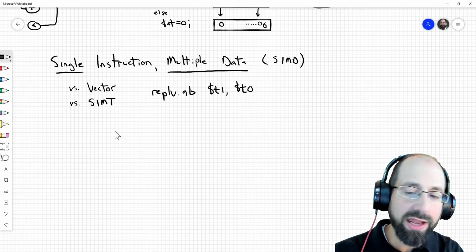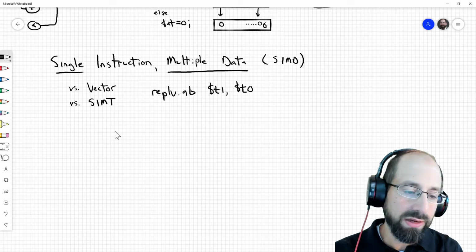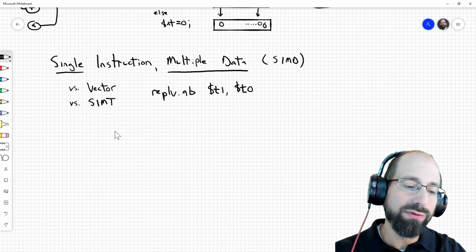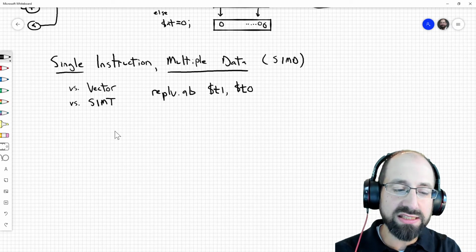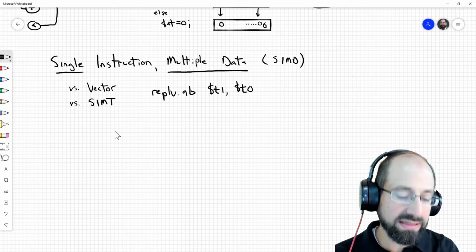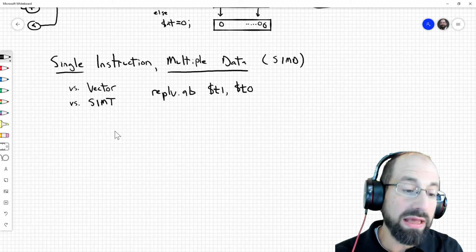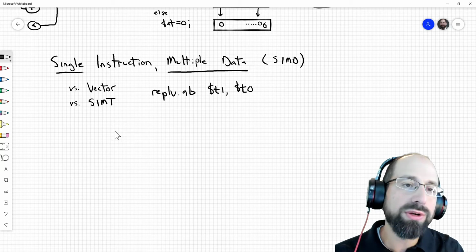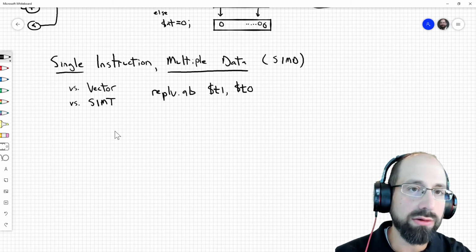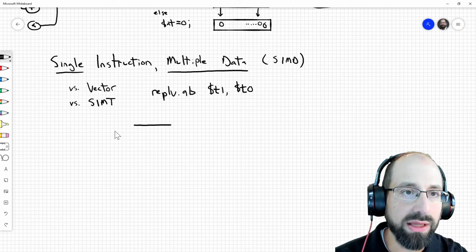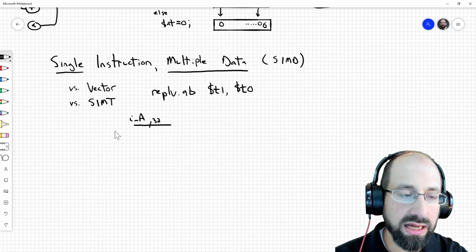And that's the other advantage of this SIMD mode of operation. It does not necessarily require a clean slate redesign of your ALU. Via relatively small tweaks of the existing ALU, or just controlling the input to your existing ALU, you may be able to implement these instructions with very minimal overhead overall. Well, how would we do this one? We already have our ALU that you've built or are in the process of building, that has inputs IA and IB. These are already 32-bit inputs, and those are the values coming straight from the register file.